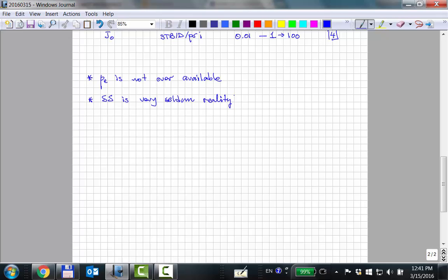If you stop any time during the life of the well, at year 1 or year 6 or whatever, and take that as a snapshot in time, the well is behaving as if it was in a steady state condition, meaning you've got pretty much the same mass flux everywhere. It's the same as what's coming out of the well. Okay? And that's called pseudo-steady state.